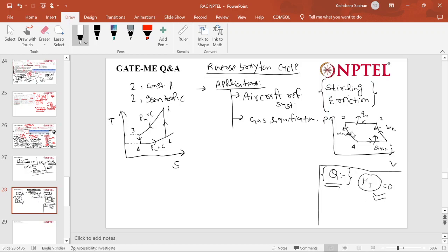So that's why we are simply using the expansion valve there, and here we are using a turbine because here temperature is pretty much high. Here temperature is approximately 200 degrees Celsius, 250 degrees Celsius, and here where this 4 point is, this is close to 30 degrees Celsius. So very much power we are going to waste if we simply waste it here.